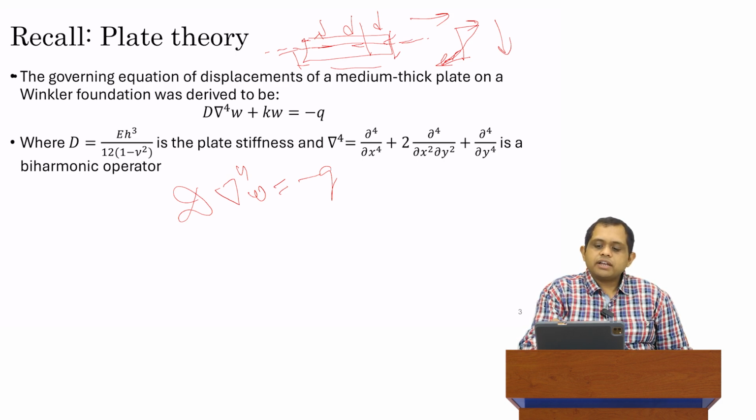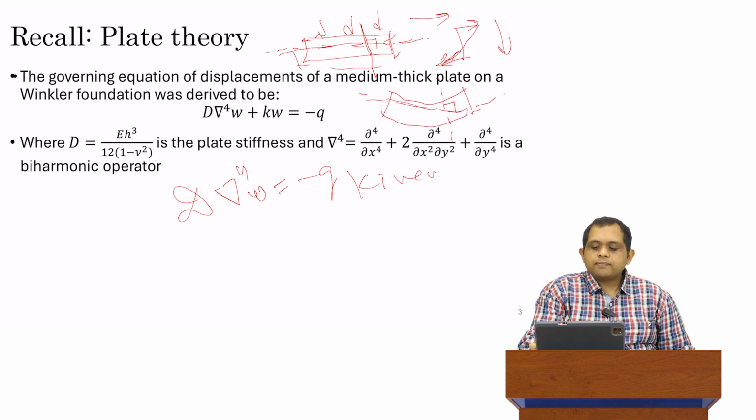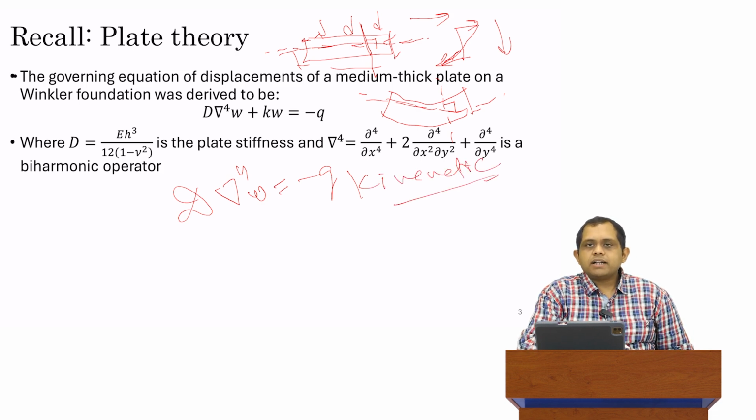In the unloaded condition, if we have any plane which is perpendicular to the neutral plane, that means the angle between the neutral plane and our arbitrary plane is 90 degrees, then after bending, if the plate bends as I'm drawing over here, and we draw the same cross section, the same plane, then that angle continues to be 90 degrees. So planes which were perpendicular to the neutral plane before bending continue to remain plane after bending. It turns out that this particular constraint, we call this a kinematic constraint. When we apply the kinematic constraint, it actually simplifies a fair amount of our analysis.